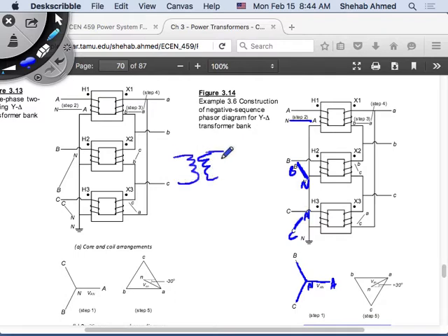This transformer will always be represented in a single phase equivalent circuit. In a single phase equivalent circuit, the transformer will be a transformer. If it's in per unit and you properly chose the base and it's a star star or a delta delta, it's eliminated. You eliminate it completely. If it's a star delta transformer, you cannot eliminate it. It will be there, and it will be represented using a phase shift if you properly chose the base.